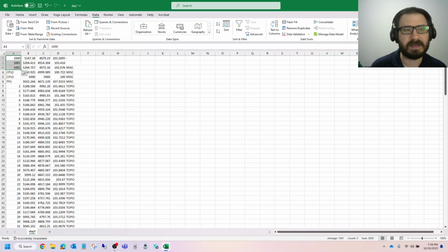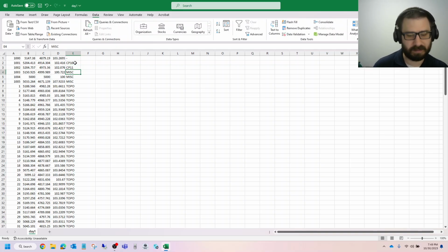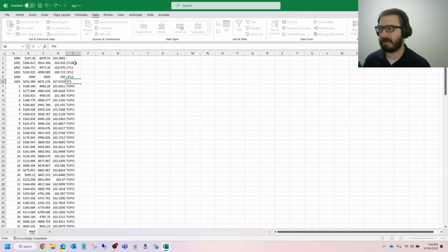We've got to get rid of these control point codes. But maybe what we'll do is go back here. We'll say this is CP10. This is CP11. This is CP12. You know, something like that. CP13. And maybe we'll call this turning point 1, what have you. I'm being fast and loose with my coding here, but in the preparation of your drawing you should be much more specific with how you code this, because this should match the notes that you collected in the field.